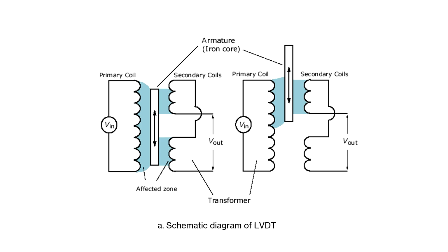On the right, we can see a displaced core. So when we move the core in or out of the setup, the core comes in front of any one of the coils, thus changing the flux in the particular coil and hence the mutual inductance and hence the EMF. So we get a difference in EMF between the coils which can be measured using different signal conditioning units.